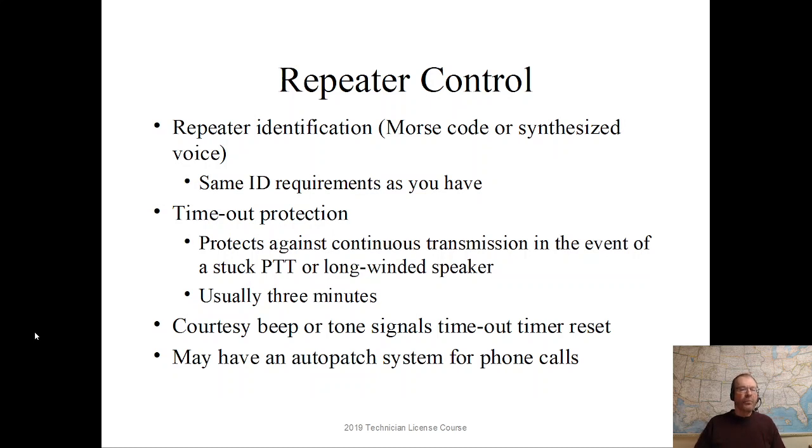Repeaters are set up too to have timeout protection. Sometimes these little things, we carry them around, we put them in our pockets, they go in our purses, they go on the seat beside us, and sometimes they get sat on inadvertently. What happens then is this little push-to-talk button will be activated and we don't know it.